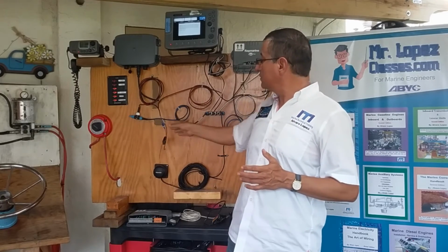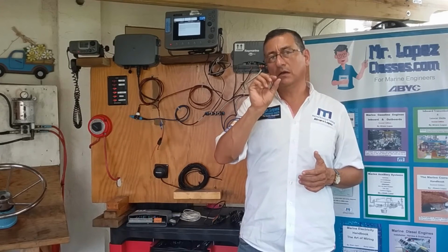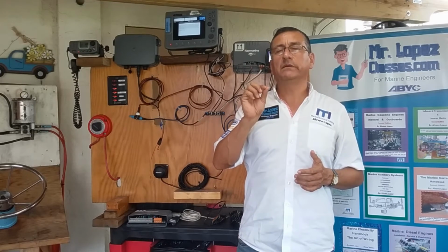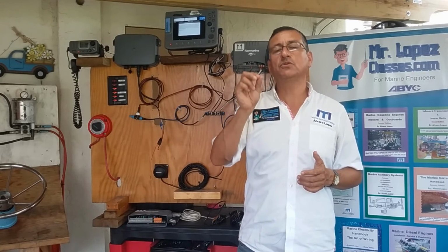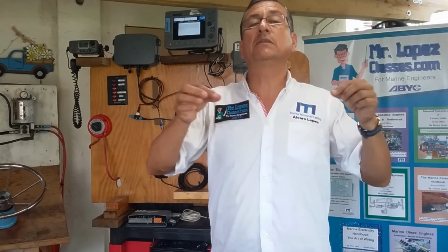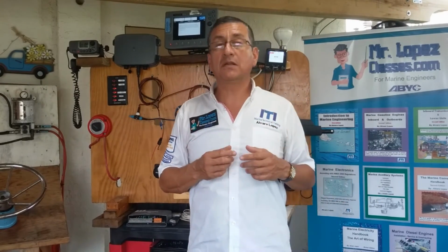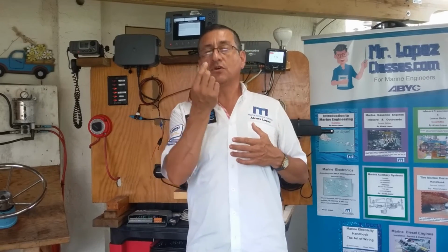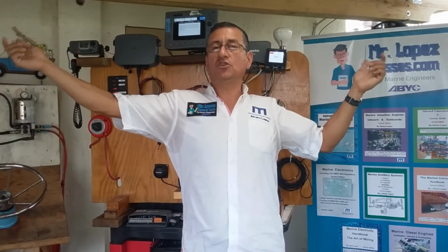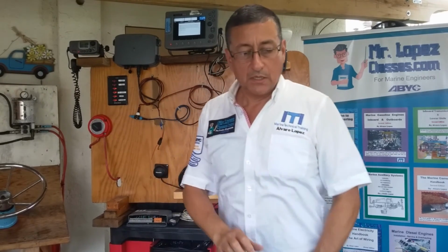If you have two sources, or if you have 3 sources, you can install fuses of 3 amps or 2 amps, depending on how many sources of power you install in total in the backbone. If the backbone is bigger than 100 meters, the recommendation is 1 source in the middle and 2 sources at each end in order to keep the balance on the backbone.